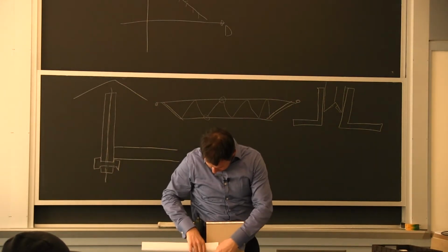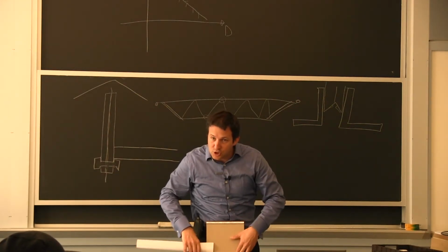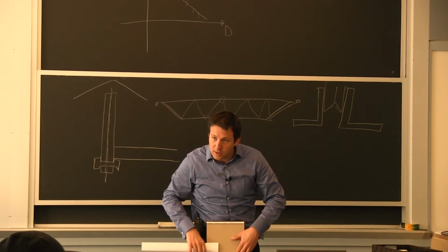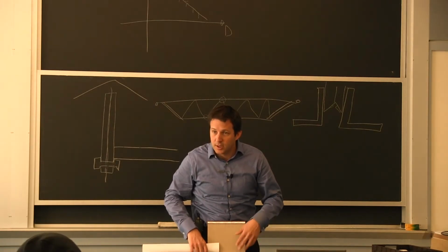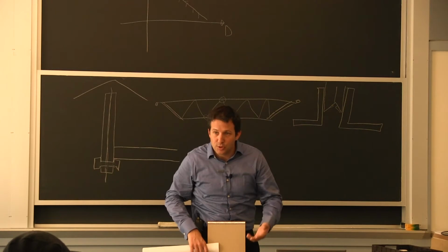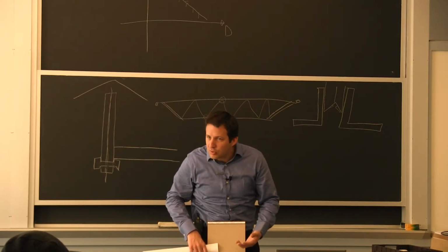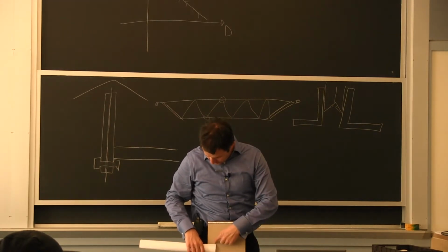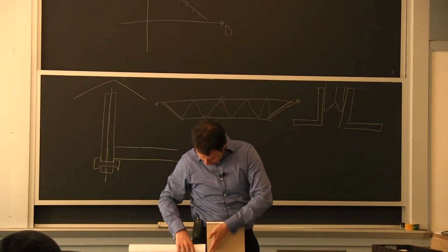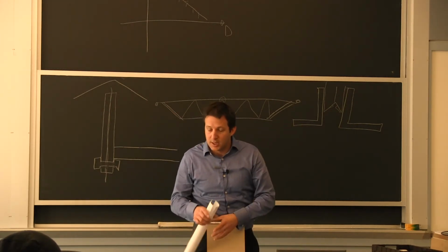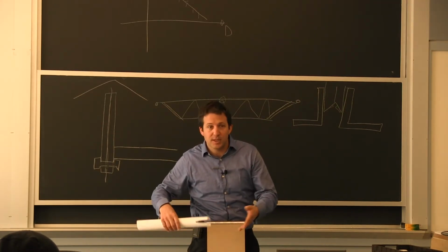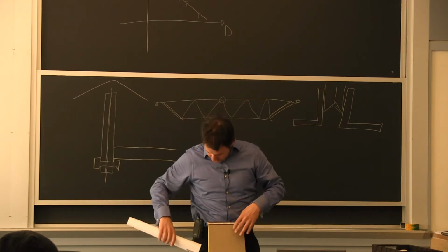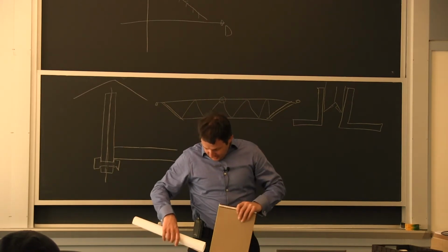If I put the weld here and here, it's going to be loaded in shear when I'm trying to pull out. It's a much better way to apply a load on a weld than in tension. Even the AWS will give you maybe a factor of 2 in fatigue strength for pulling this way as opposed to trying to weld the end. The other reason is that it is a hollow tube, so if you try to weld the end, you have to put a plate, and it is more complicated. But when we talk about a gusset plate, that's what is going on.